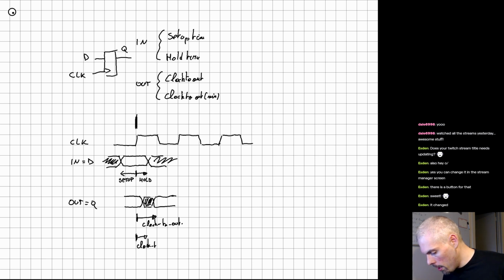Sometimes the flip-flop will actually guarantee that it won't switch value before a certain time. So after the clock edge, up till here, the old data is still present, and the flip-flop guarantees that it's still present. And that's useful because if the next flip-flop has a hold time, well, obviously it's very practical that the flip-flop just before doesn't switch instantly, right?